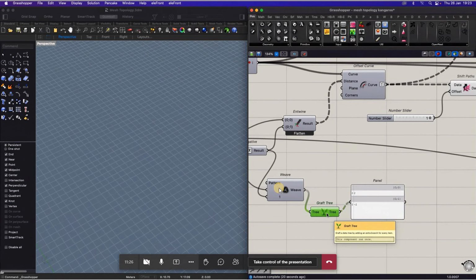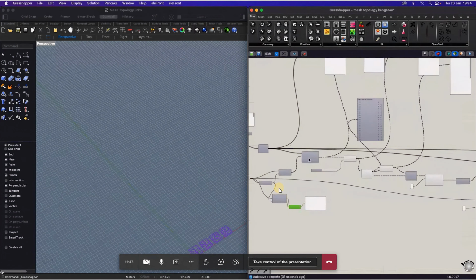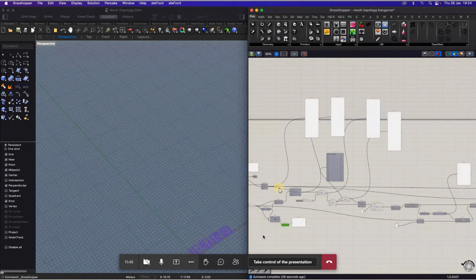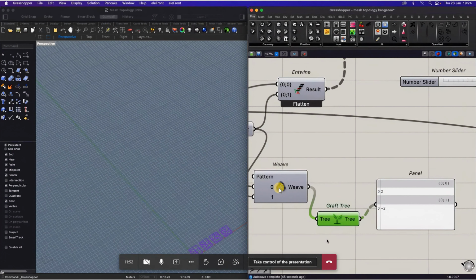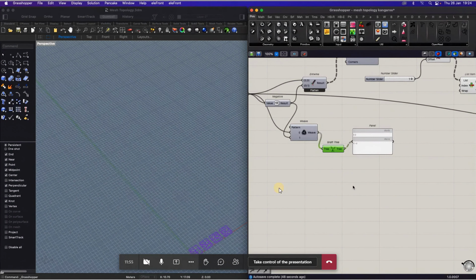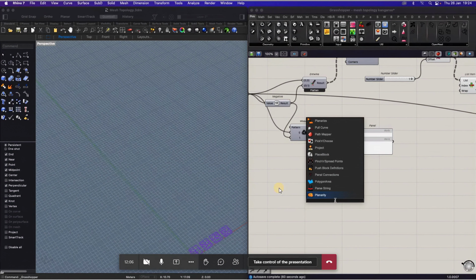I'm no expert and I'm still getting my head around it, but essentially what grafting does is create two tree branches. Whenever the output is used, the component will compute both of these. If it was just a list, it might not do it. So the thinking behind it is that graft doesn't mean mapping. It's more about the output being, instead of a list of just two items below each other, which would do something else, two branches.